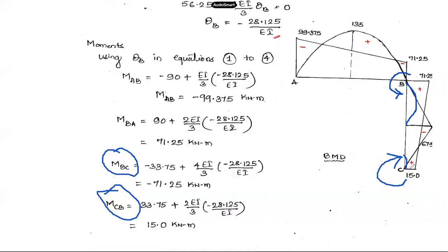So that is how I'll identify the ordinate direction for the vertical members, whether it is bent towards left or right. In the same direction, I'll take my ordinate. Anti-clockwise, it is coming and hitting this member, bending it outwards. Clockwise, it is coming and hitting this member, bending it outwards. On that basis, I've decided in which direction I'll take the ordinates. So that is clear, how this ordinate came into the picture for this member BC.